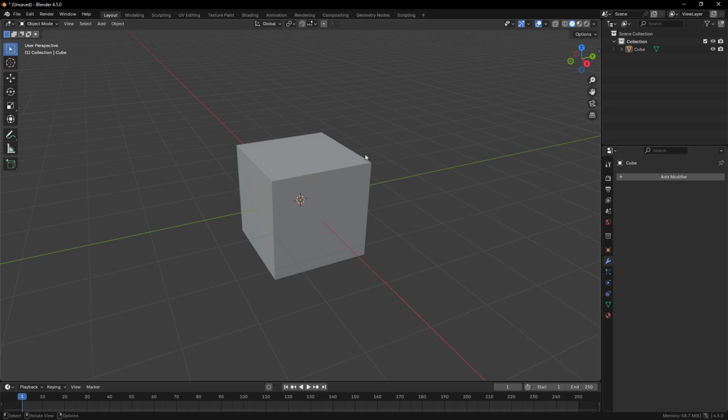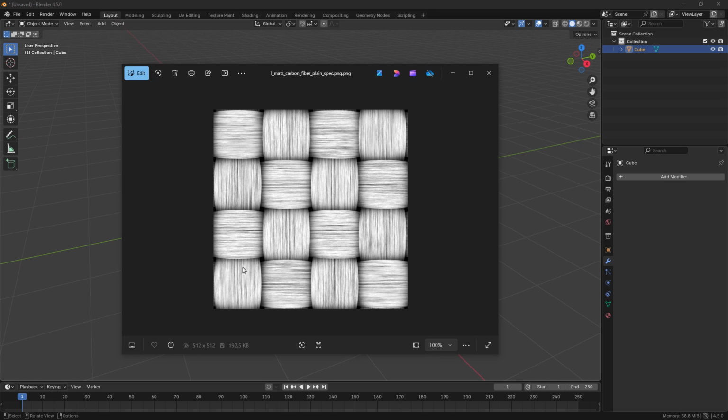The big thing we need to understand is that in order to do this, your mesh element sizes, whether they're quads or tris, need to be small enough to capture the detail you're trying to add. When we look at an image like we have here, there is a lot going on with these gray bands that give us the appearance of a true carbon fiber fabric.